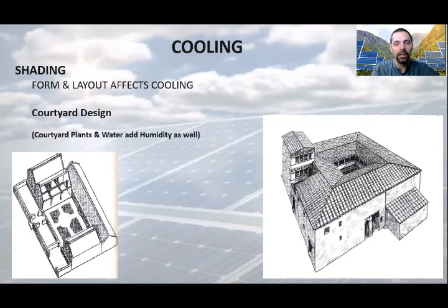During the day, as the courtyard heats up, the cool air is drawn from the rooms to the courtyard, creating a cooling breeze effect. At night, heat from the courtyard roofs and stone floors causes reverse convection, drawing heated air to the back rooms. In wintertime, the process is reversed. The heat is left in rooms by shuttering the windows and openings to retain the heat.